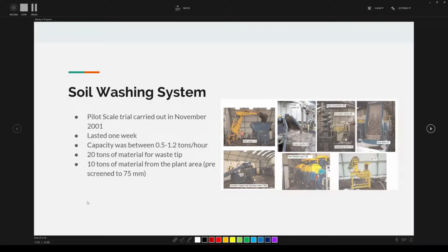There is also a primary cyclone, which is used separately or in series, and this segregates the material that's less than 2 millimeters into a discharge product containing mostly sand-sized materials and one containing silt and clay. In addition, hydrocycloning also removes a significant proportion of water from the sand-sized discharge product. This partial dewatering to 60 to 70% water by weight improves the efficiency of the downstream scrubbing process.